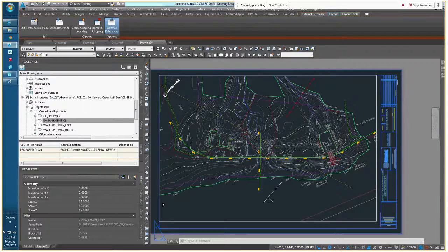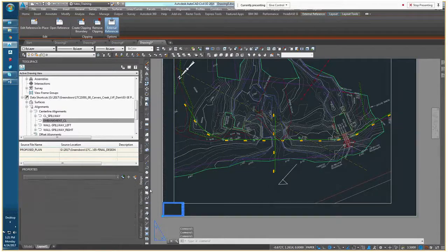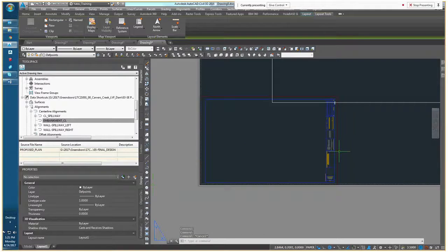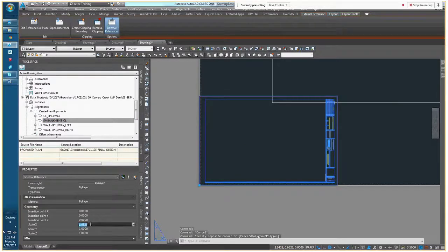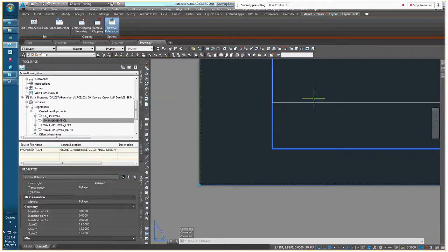If this object was scaled to 1, but you wanted it for some reason because of other scale issues to be scaled down by 1/12, please don't ever use 0.08333, even if you carry it out to the 10 millionth decimal point. You can very easily, within the scale X, scale Y, and scale Z properties, use 1/12, 1/12, 1/12. And it will always scale properly versus trying to use the decimal approximate.